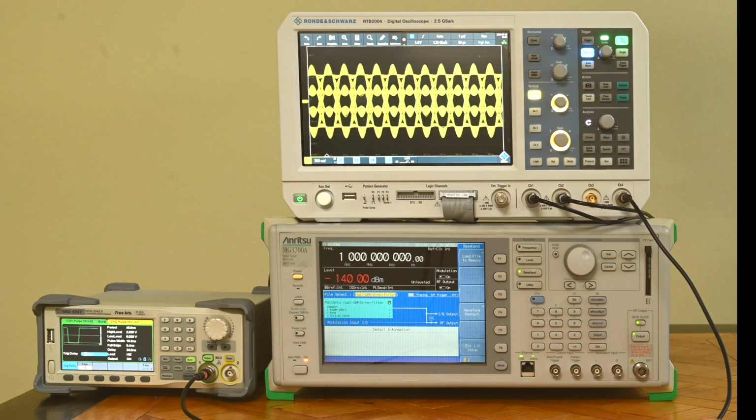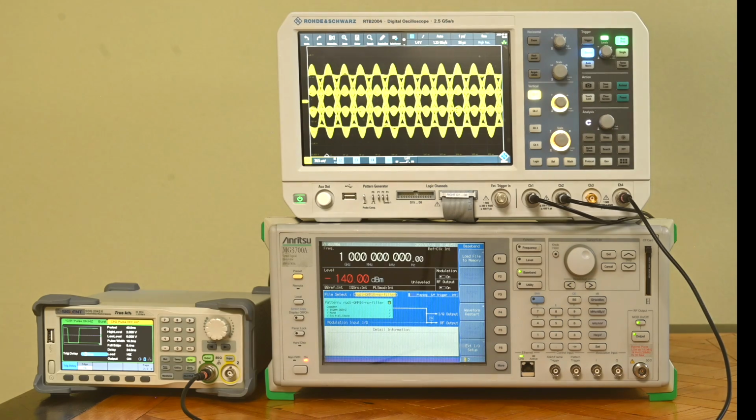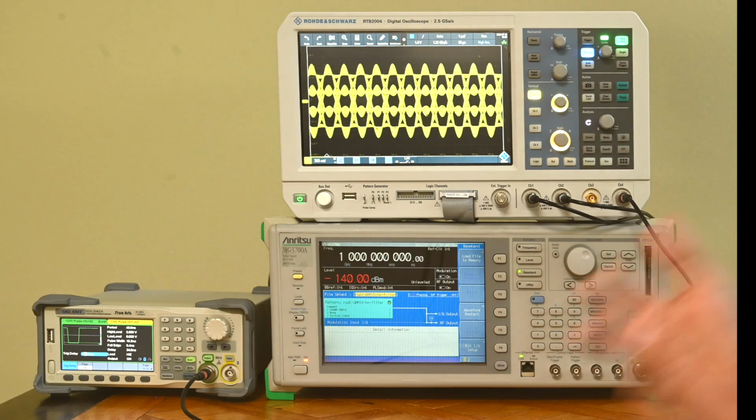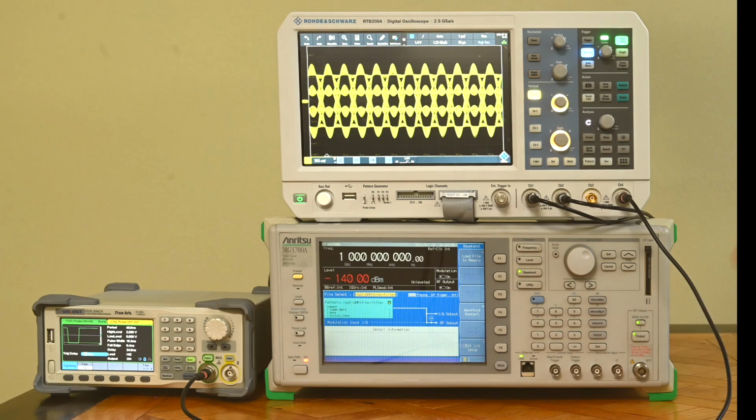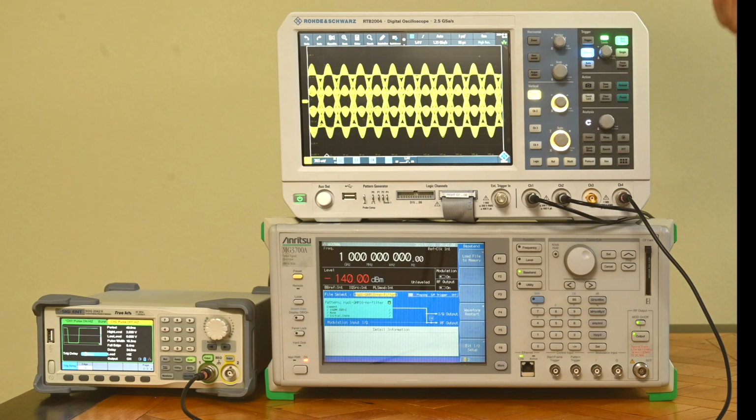Now, what we need to do basically is to tell the oscilloscope to only look at the particular point in time that we're interested in observing the signal, when we feel that the IQ signals are at the moment they should be sampled to know what their values are. So it's somewhere on this waveform, maybe not exactly on these tops, maybe somewhere else, but we're going to try to find out. Now, how can we design that process?